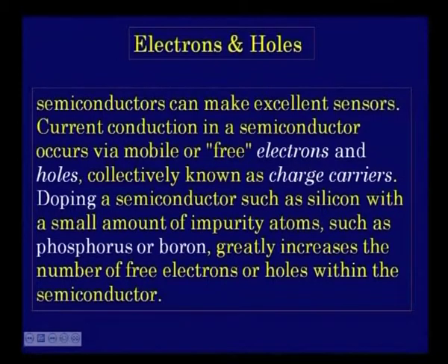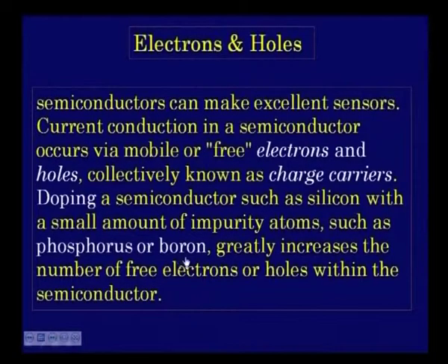The current flow can be manipulated in semiconductors by changing the number of free electrons and holes by doping, as I told you, with aluminum or phosphorus, or similarly you can have boron, and again phosphorus. You can have 3-5 compounds. Some of the elements in the third column of the periodic table on the right side or the fifth can be substituted in the place of silicon.